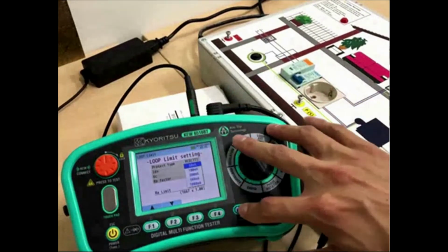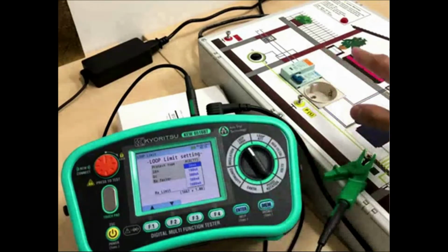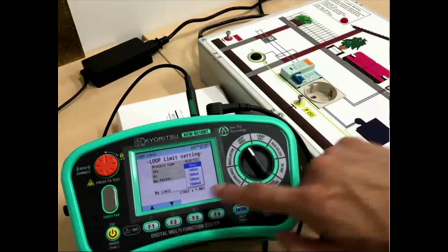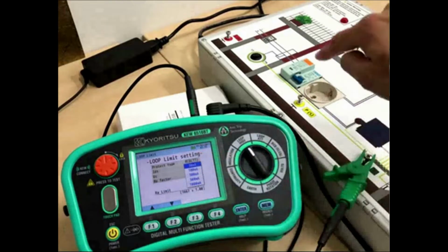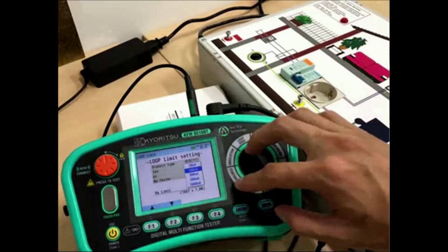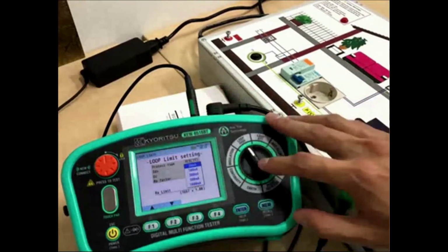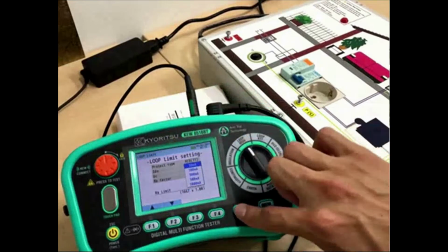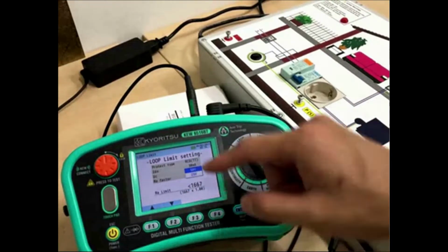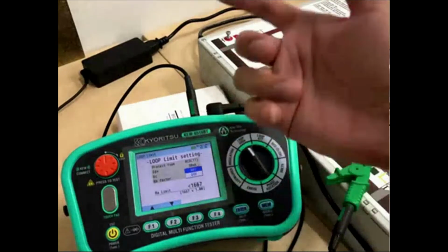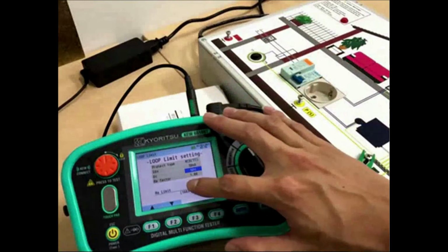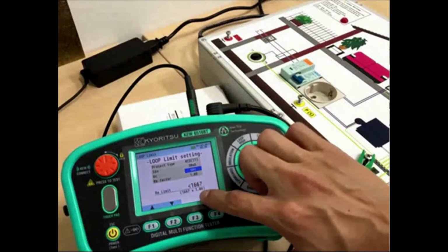Then this one, the rating current of your RCD, just now I showed you it is 30 milliamp. You must choose according to your RCD rating current. So if you choose 100 milliamp, cannot. Must choose 30 milliamp. Enter. Then safety touch voltage 25 and 50 volt. We choose 50 volt for general. Enter. Then RA factor. If this RA factor is 1.